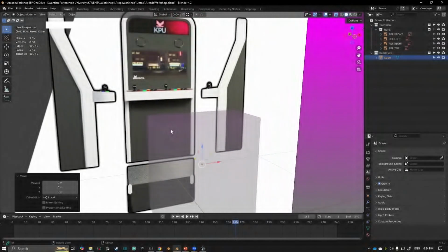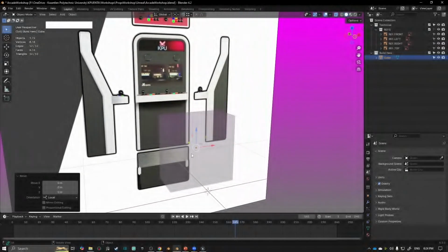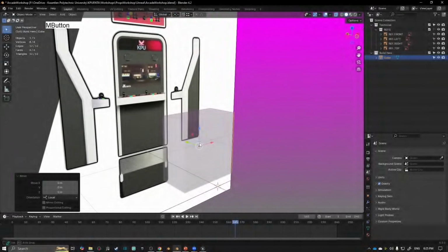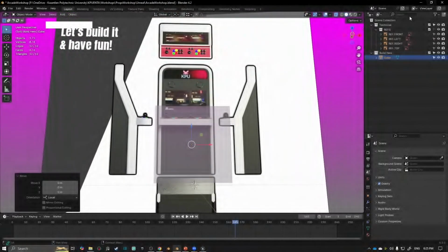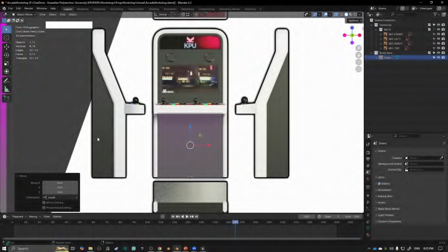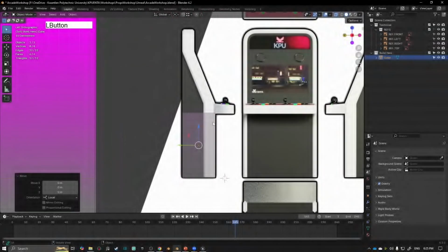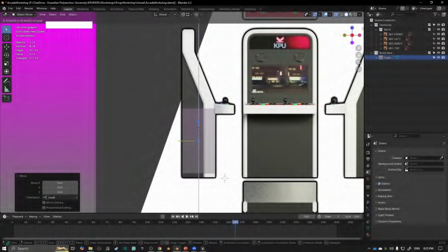Okay. Now, depending on comfort levels, some people could just duplicate the cube, move it up, duplicate the cube, move it up, etc. We're going to just model it like we'd be modeling it. Up until this point, we've been using moving, rotating, scaling, that sort of stuff. But now we actually need to get in and do some editing. Actually, what I will do is maybe scale it up a little bit more in the Z. So S to scale, Z for height.